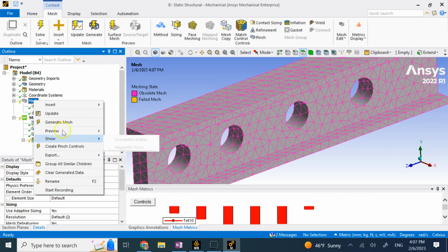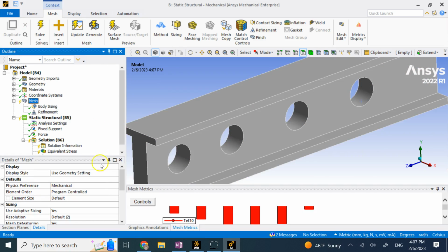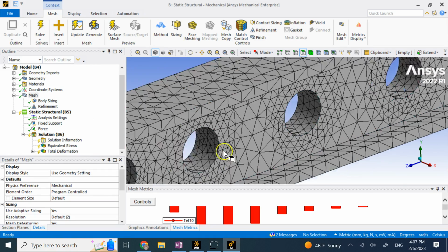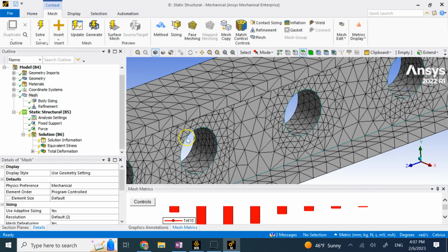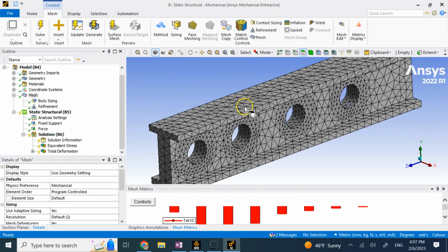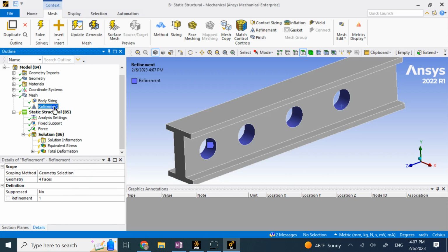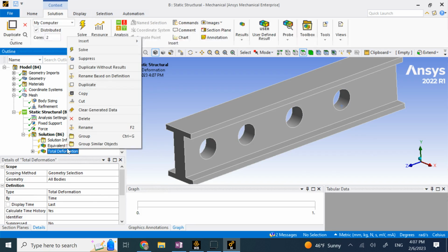And now look what happens. You see? So now clearly I have what? I have smaller mesh size here compared to here or here. And that way I'm still able to get accurate results, but the number of nodes is not basically skyrocketed because the global mesh size I have not changed. So this is the global size, and this is the refinement, local mesh. But as I said, we can do adaptive size control. What does that mean? So here is what I'm going to show you.